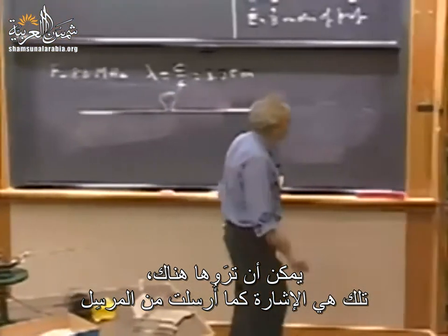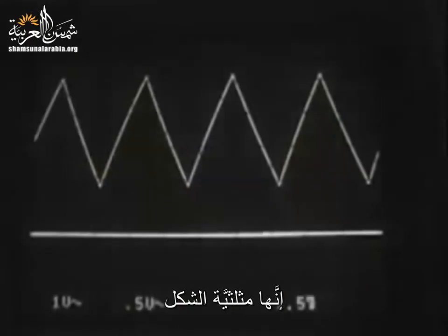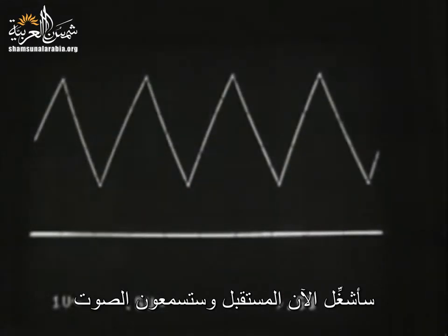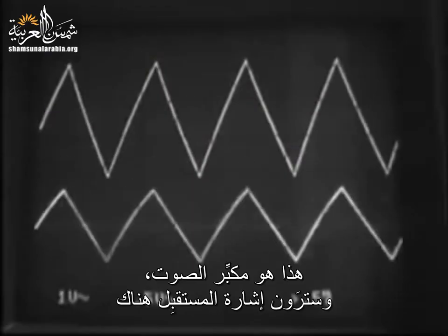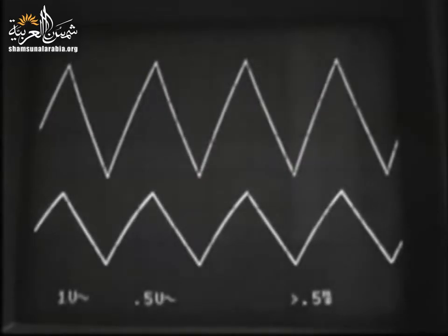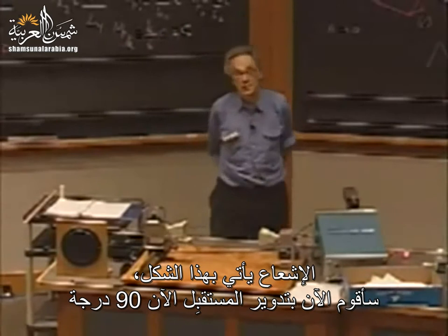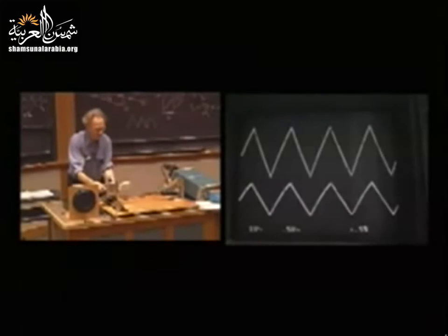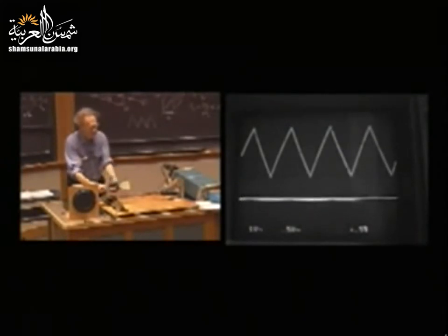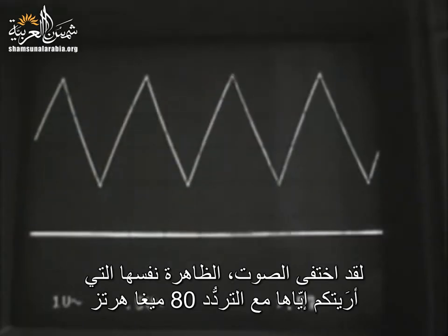That is the signal as it is sent by the transmitter. So that is the triangular shape. And now I will turn on the receiver, and you will hear the sound. This is the loudspeaker, and you will see the signal of the receiver there. So the radiation comes in like this, and now I'm going to rotate the receiver 90 degrees, and it's gone. The same phenomenon that I just showed you with the 80 megahertz.